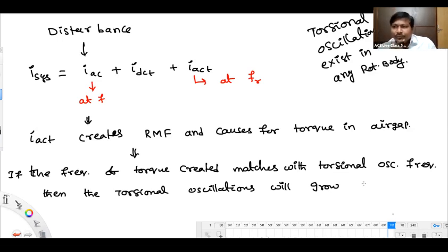Listen please. Whenever these torsional oscillations become severe, if you think about your mechanical system, we have a rotor body, shaft, and turbine. Which is the weakest one among the three? In the generator, that will be the shaft. The shaft will be the weakest one. So that shaft is going to experience some sort of mechanical damage. This we are going to call shaft fatigue in the alternators.